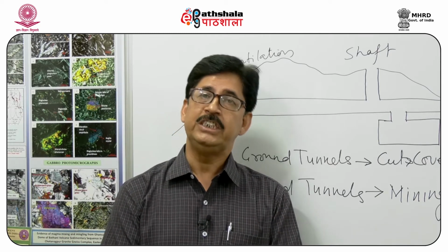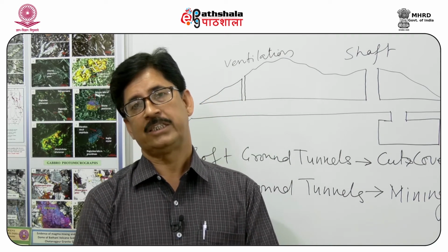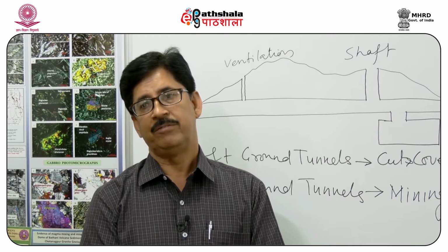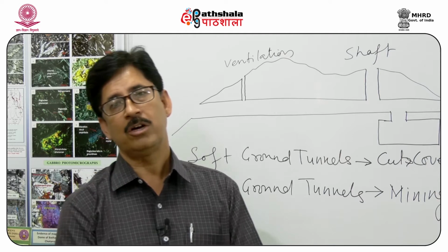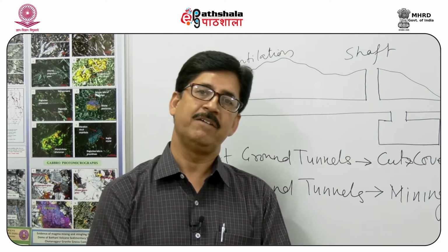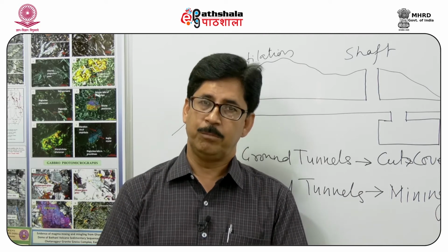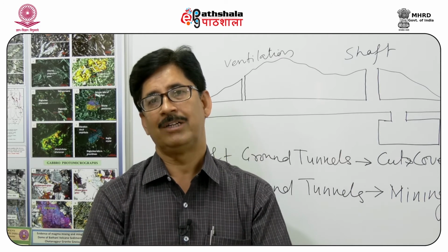Nowadays, machines are much in use for excavating through the rocks. We have different kinds of machines which excavate through the rocks, specialized for shaft boring. We call them shaft borers. We have boring in which we start from a tunnel and go upward, that is called a raise.